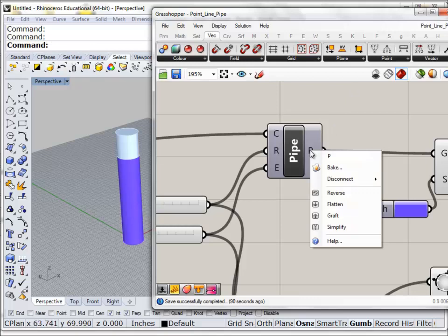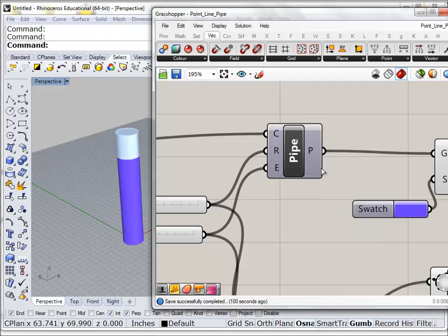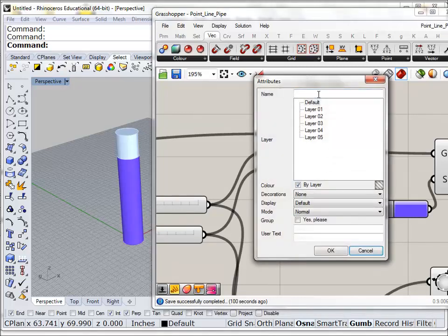If you, for instance, are running an operation and then you come back to Grasshopper, then you decide that you want to bake, you want to make sure that nothing is in your command lines, because now we're finally trying to connect Grasshopper back to Rhino. So we're going to tell it to bake, and we can pick whatever layer system you have. For instance, I'm going to just take layer 1, and we can tell your geometry to be grouped or not.